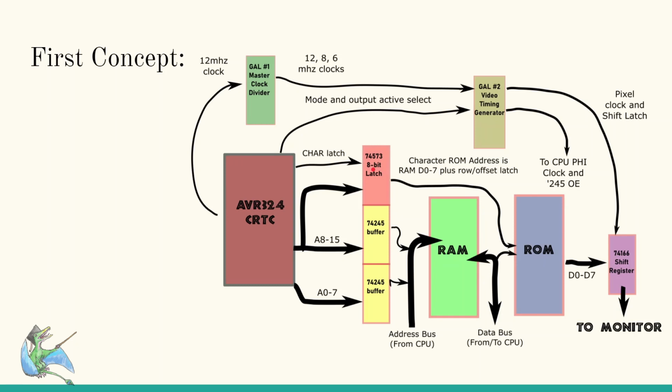Now a latch is a simple electronic device where you have 8 lines going into it on one side, and 8 lines coming out at the other side. When it's not latched, if there's a change on this side, it goes straight through to the other side.